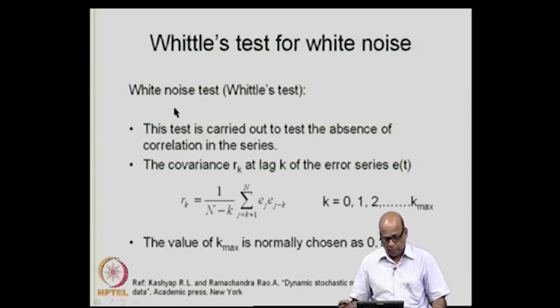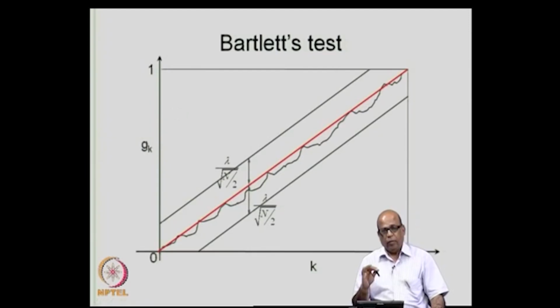Now, we will see the white noise test. For the periodicities we now have two tests, and typically we prefer Bartlett's test because of its ability to test all the periodicities in one go, and also computationally it is very simple. That means you simply calculate G_k, much like your correlogram, you formulate the periodogram.